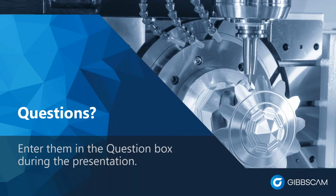Absolutely, yeah. On a 3-axis mill, as we were displaying there, you can easily use the 5-axis module, lock out the rotary axes, and have yourself a 3-axis toolpath creation engine there. It creates very strong 3D toolpath operations. There are also, which I didn't show here, some very effective roughing strategies within the 5-axis, as I was saying, that adaptive roughing. It's available in different sections of the 5-axis module.